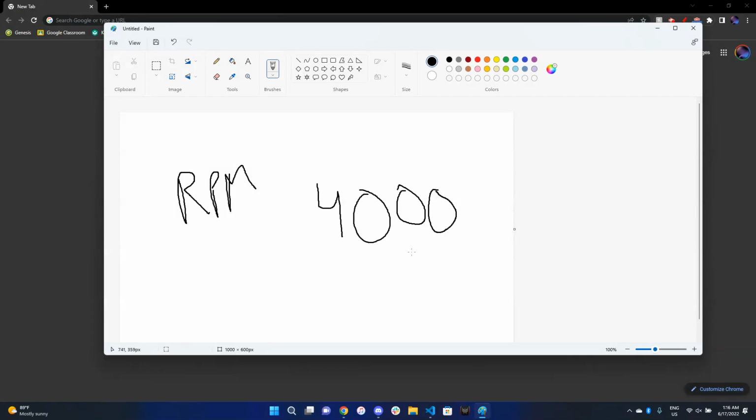We can use a sensor. We can get the sensor on the Falcon, which we call an encoder. We can get the encoder data and effectively command our motor to move at this exact velocity. Now, the tricky part with this is determining how exactly we are going to get to that velocity in the first place.